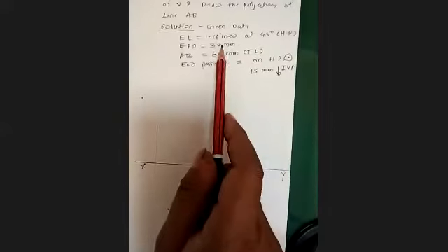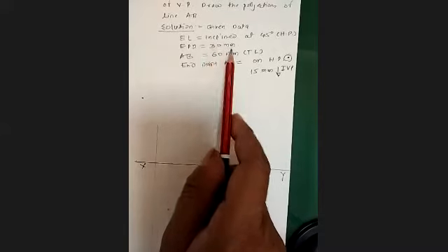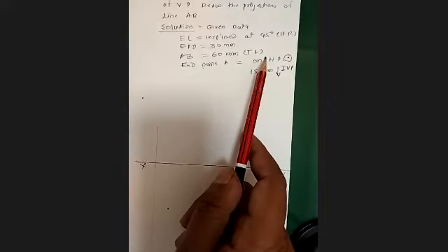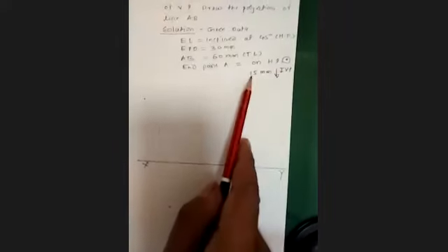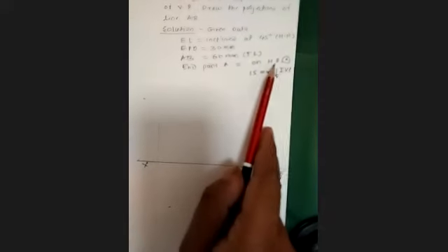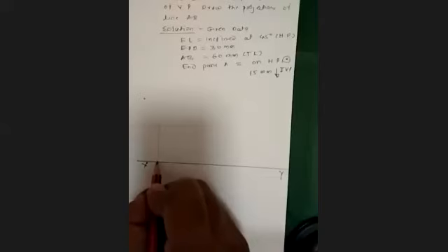Okay. So you have to judge which point you can take first. Suppose the elevation is 45 degrees; unless you mark the point, you can't get that 45 degree inclination. End projected distance you can take on the XY line, not an issue. But AB 60 millimeter true length, you can't take yet. End point A on HP and 15 millimeter in front of VP. When the point is on HP, your first point, that is A dash of your front view, will be seen on the XY line.